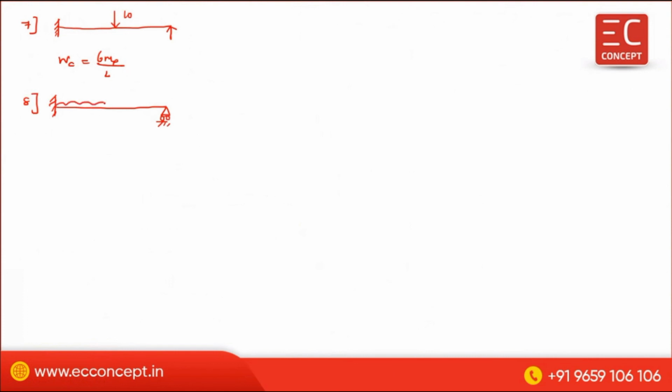Now the plastic hinge will be developed at a distance, which you have to keep in your mind, from the free end to the maximum bending moment occurring point, equal to 0.414 L, and the collapse load is equal to 16.656 MP divided by L square. So this is also an important examination question.